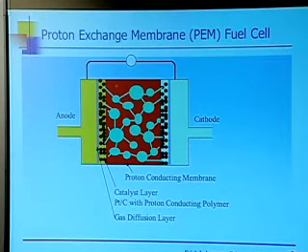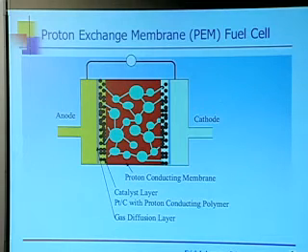That is, it has areas in red that look pretty much like Teflon. And then it self-assembles so the sulfonic acid groups are adjacent to each other. And so you have other areas, these green areas, where you have hydrogen bonding between sulfonic acid groups. If you expose this material to water, then it readily absorbs the water, and it absorbs it in these areas that are acidic, not in the red areas. And so you end up with these little pools of water in the material and little channels lined with the sulfonic acids that interconnect those pools.